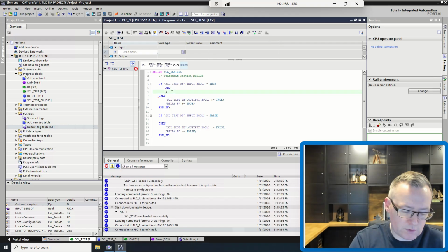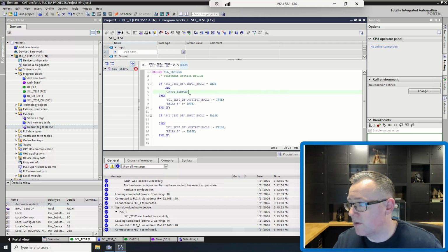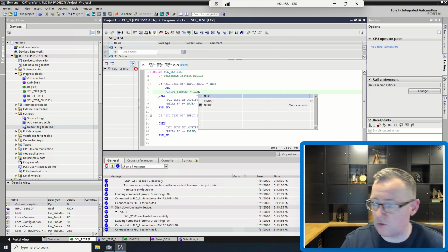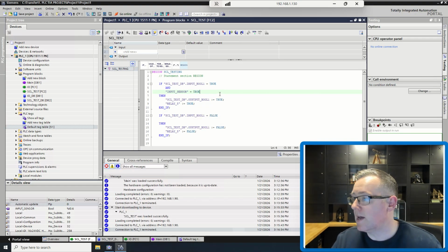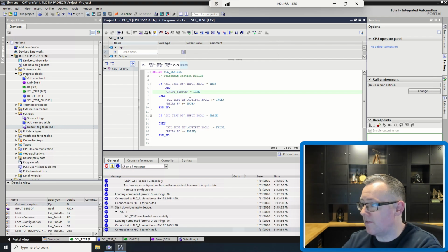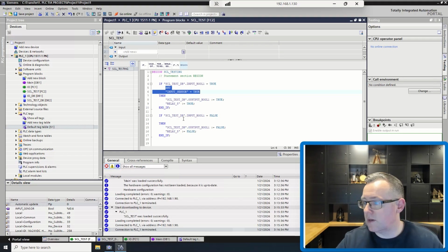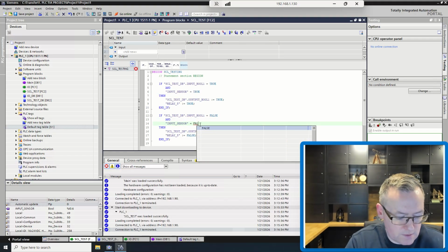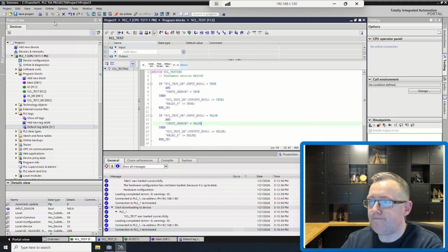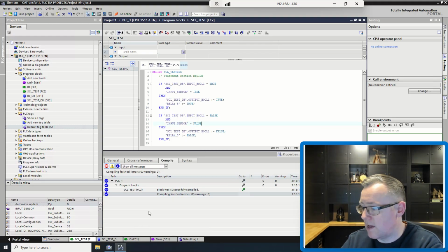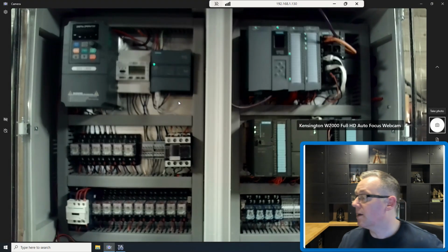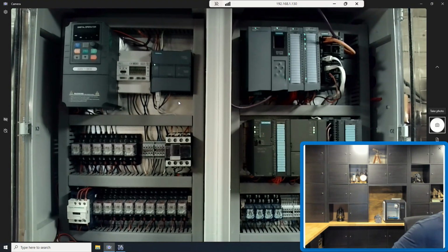And now we're going to look for input sensor, and see if it is true also. Right? Essentially it means that this will kick off if input sensor is true. Okay? And we could of course put the same logic back again if we want. So there's two conditions here, and we will go down here and simply say false. Okay, so I will compile that. And just for anyone to see here, the input sensor, I'll show it quickly on the camera. I'll just be a moment.